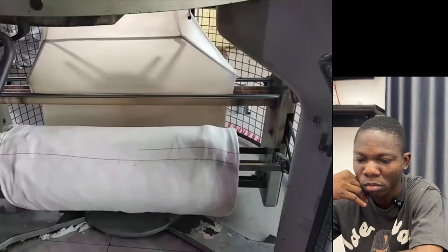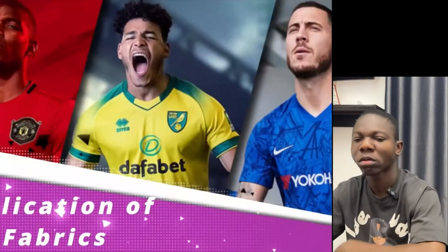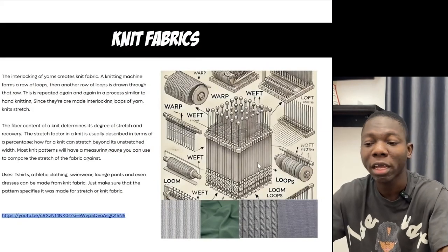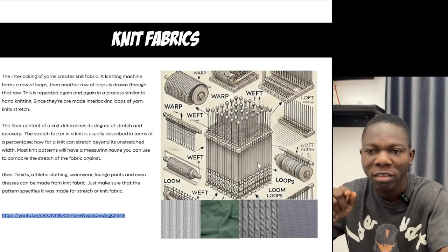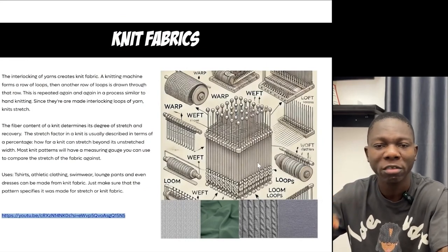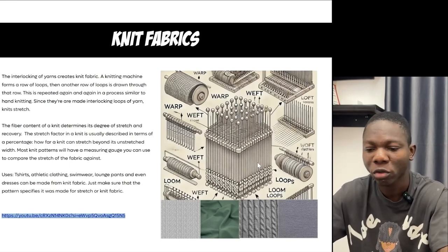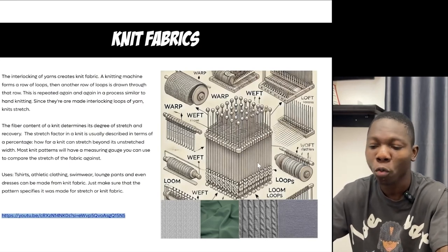It has particularly a comfortable form of fabric structure for sports and casual wear. So the main difference between a knit and a woven is that for a knit fabric, you can usually see holes in between it because the materials were not bonded together by a loom, as in the case of woven. So that's the major difference to easily spot out fabrics that were made by the knit or woven process.